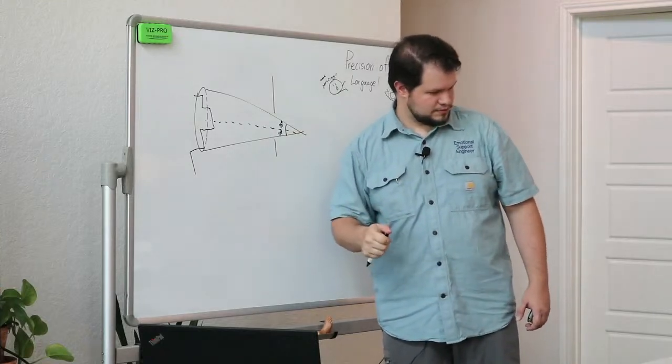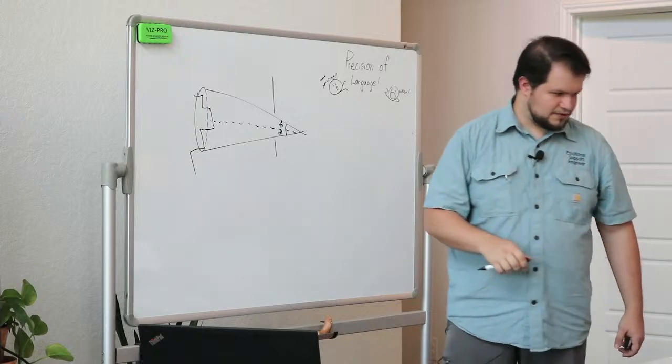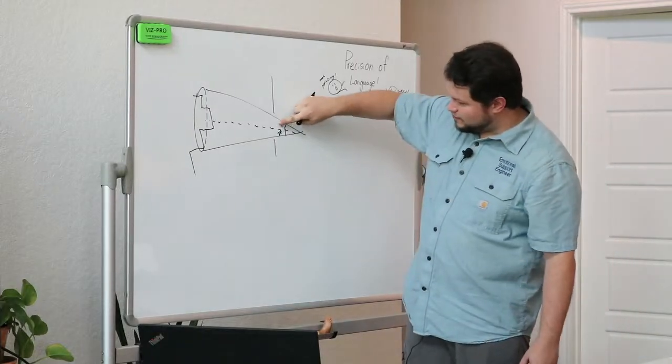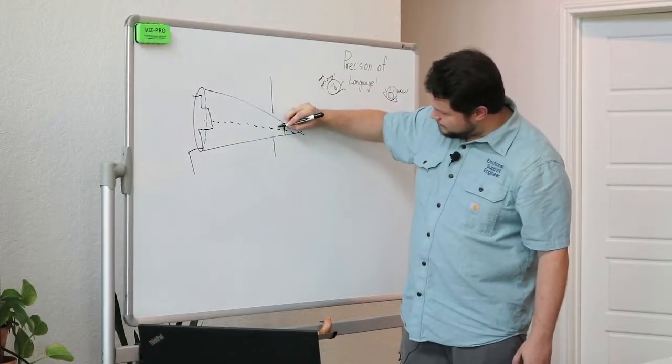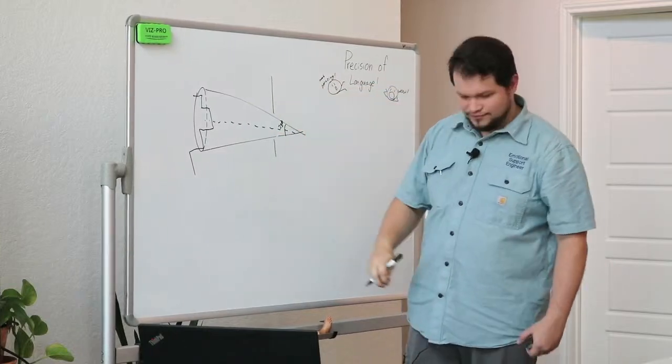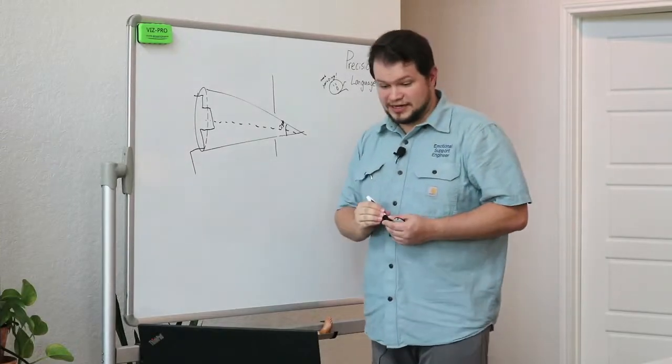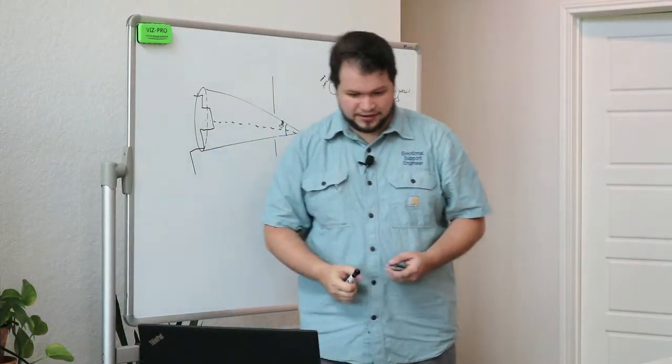You found what kind of angle it is? Thank you. They pulled up the spec. It is actually 25 degrees inclusive. So that's 12.5 per side. But that is a very fair question that you asked because I didn't know the answer.